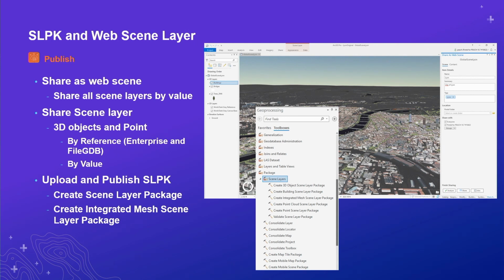In Pro, you can always reproject the data on the fly, but that always comes with a price tag. Your layer may draw slower. In case you plan to edit the data, we always recommend to do this in the layer's coordinate system. The third way of